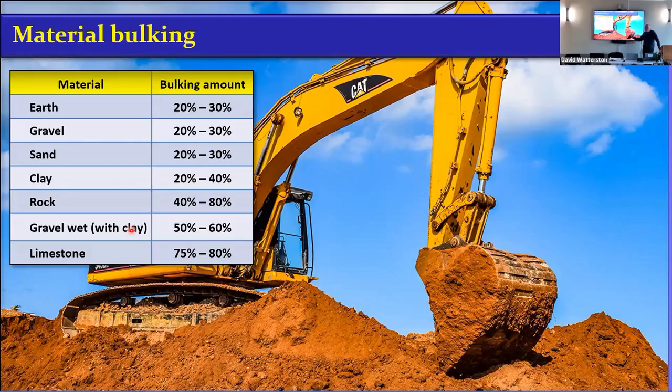Air between it. And somebody asked me, would it be different if you used a bigger bucket or a little bucket? And there's a bit of sense in that. If you've got a little bucket, you're going to create more air pockets than you would with a big lump that's all compacted together when it goes in. But it's not an exact science. You know, you're going to get stitched up with it. But as long as you're aware that when virgin ground is getting taken out, it will expand. And if you're then asking somebody to remove it, it's not what you calculated. It's what this increase is that you need to think about, how many trucks to bring in or take away.